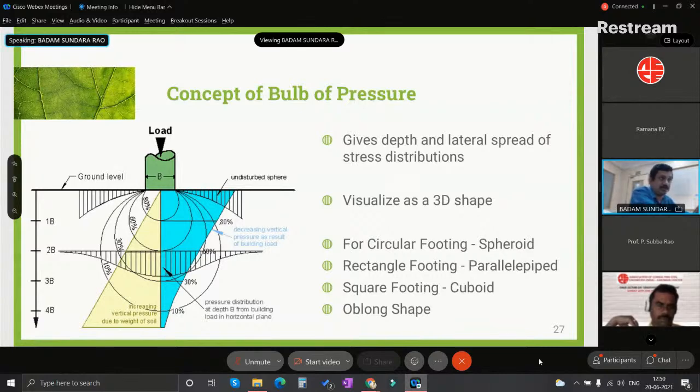Generally, in textbooks and any literature, this point is not highlighted. This understanding is very important for properly designing any foundation for load and settlements. Once we understand this concept, we can play the game with the foundation systems. Therefore, at the crux, I will explain once again. B plays an important role in the distribution of stress to the soil mass in the depth region. That is, the depth value of the stress distribution will be affected by B, and the length value will be affected by the